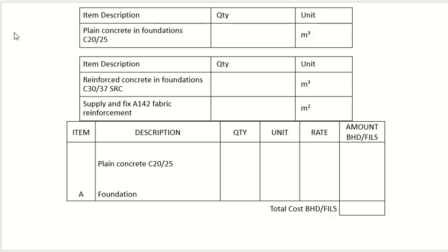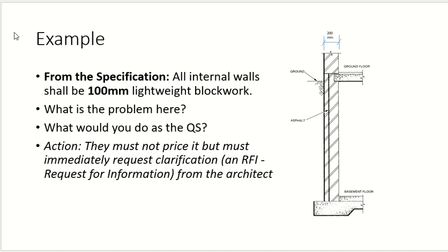Now, if you look at the previous examples which I gave you, these two items can go in separate tables on separate pages, because one is for concrete, the other one is for fabric reinforcement. So they are not usually written like this, one after another. They are done item by item. So for example, I need sulfate resistant concrete in wall footing, column footing, and underwater tank. So all items for this concrete will come together. And fabric, all items of fabric mesh will come together. One more point? Clear? Any questions? Okay, I'll show you this example next time.